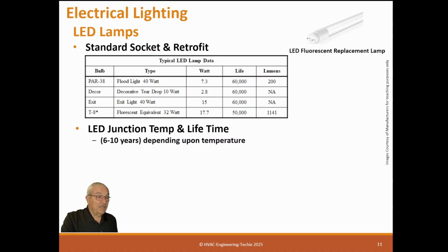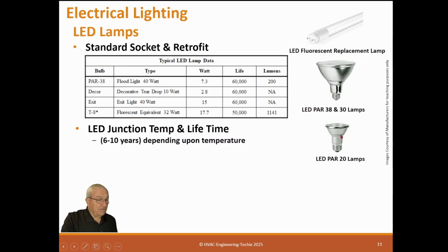Now, there is another thing about the LED retrofits I talked about. You can change these bulbs for fluorescent. You can change these in PAR fixtures. You can get small ones in PAR 20 and PAR 10. You can also get standard LED bulbs like this that are actually LEDs, with the ballast down here for the LED.